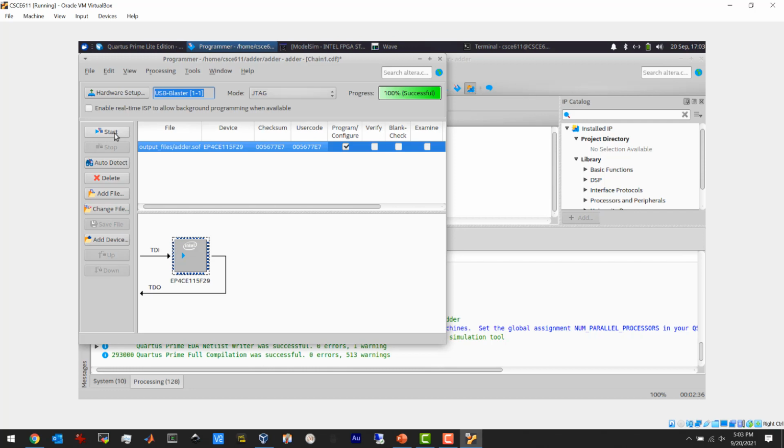The other one is for if you want to program the FPGA to implement a USB host. And if you want it to be a USB device, like a slave, then you use the third USB plug to the right. But the first one is for programming. That's the blaster, that's the JTAG connection, that's your debug program connection.